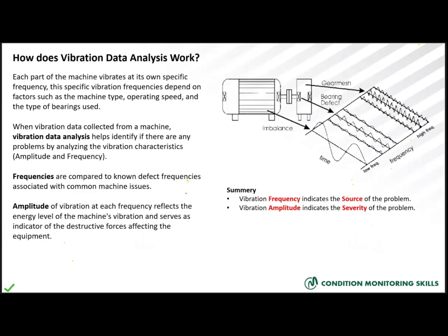Each frequency has its own amplitude, its own height. The amplitude of vibration at each frequency reflects the energy level of the machine vibration, and it can serve as an indicator of the destructive forces acting on the machine.